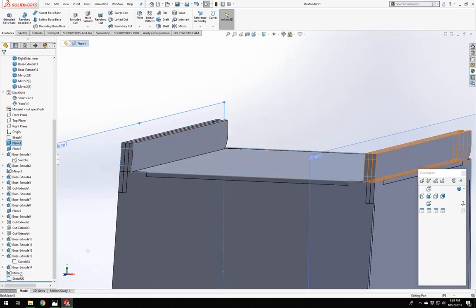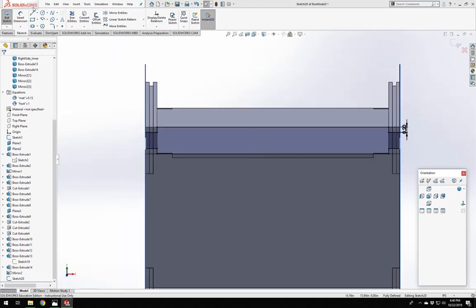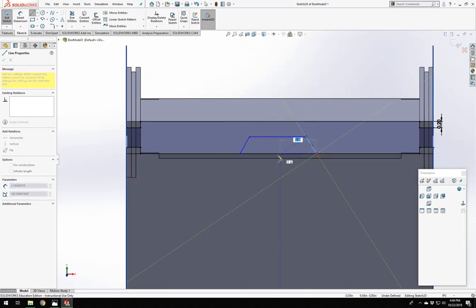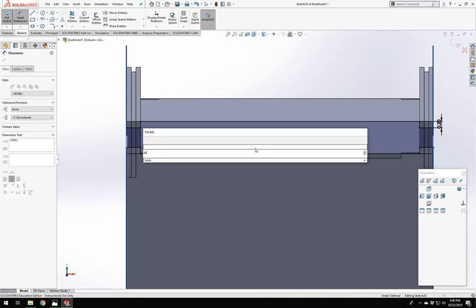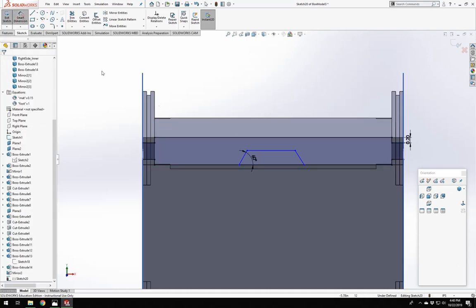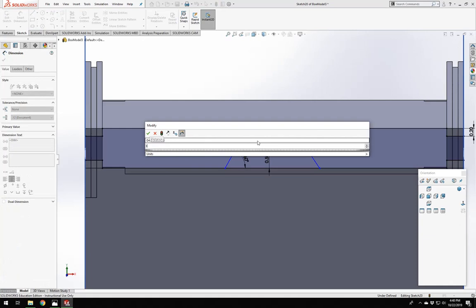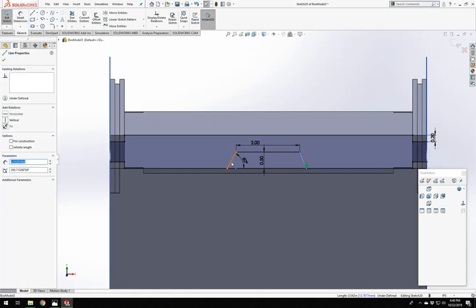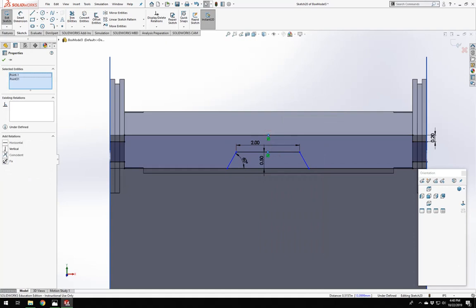But let's go back in real quick. We're going to need some way to open this thing. So maybe a handle or a grip surface, or in this case, I think we're just going to do a quick cutout. So very similar to how we've been doing the feet. Whoops. Been saying 60 degrees, I think. Sorry. Magic number. There. Grab our dimension. Three may be too big. Let's do 2. These two are equal. Then we'll select this, select its midpoint, grab that midpoint, make them vertical. There we go.